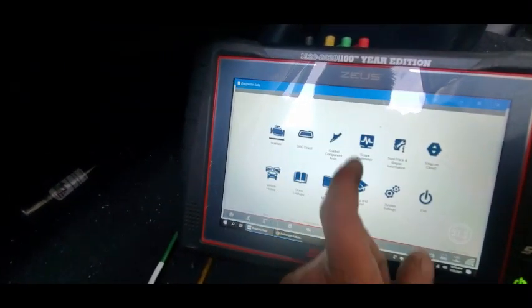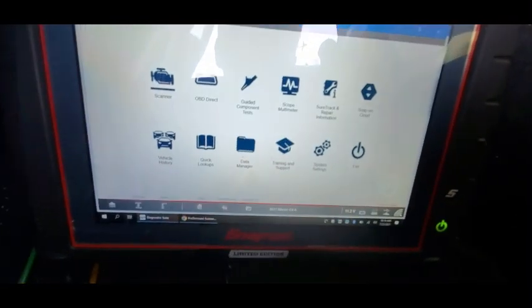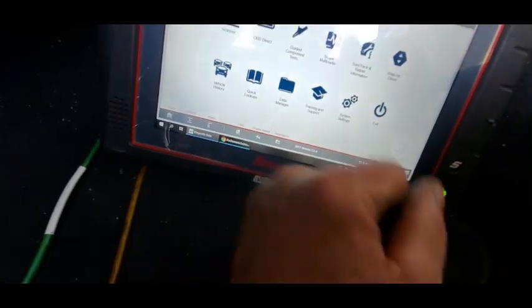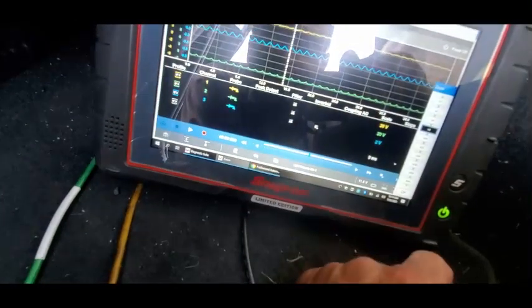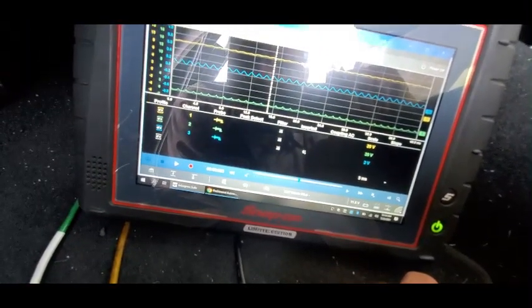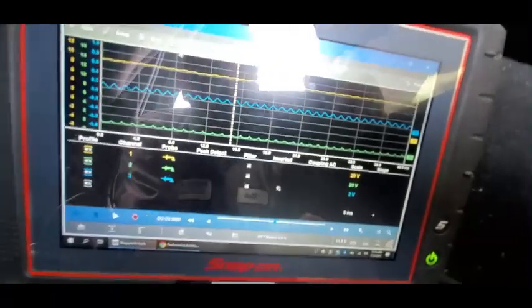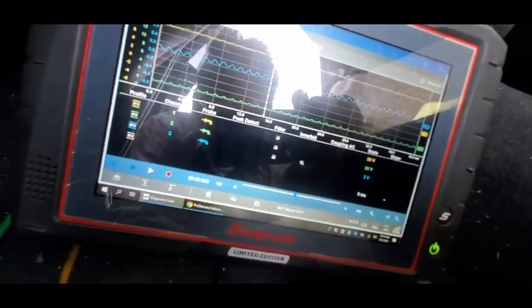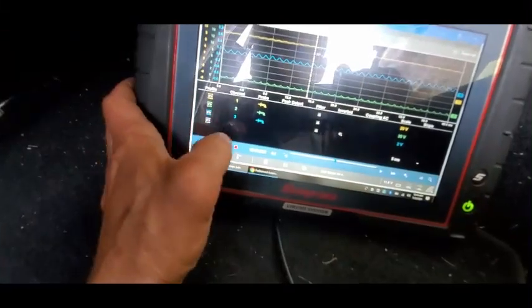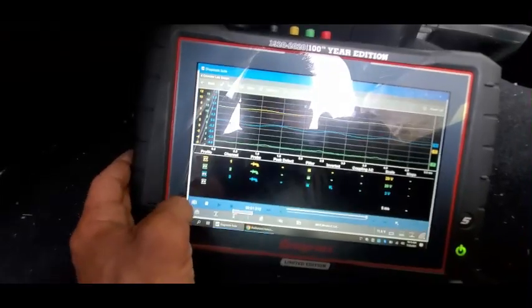Okay. You can stop. Oh, that battery's getting low. We're at 11.2 volts. No wonder. That's why my voltage is low. So, why are we only getting... It's because battery voltage is low. Damn it, I don't want to put a tender on this. Hold on. Alright, crank her again. Yeah, that battery's about ready to die.